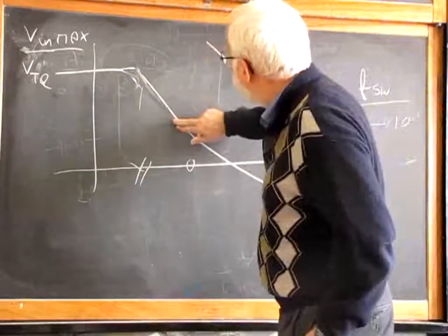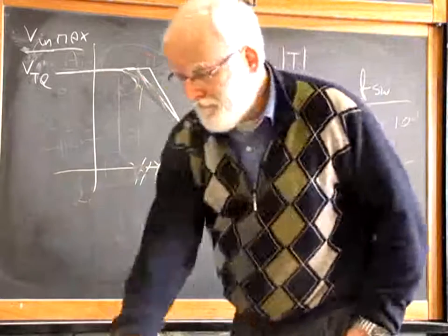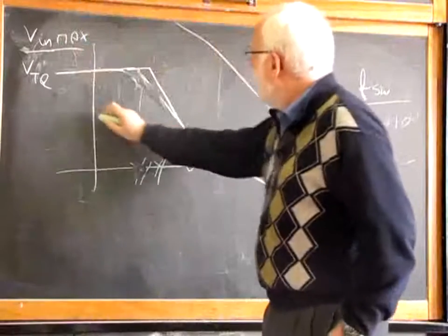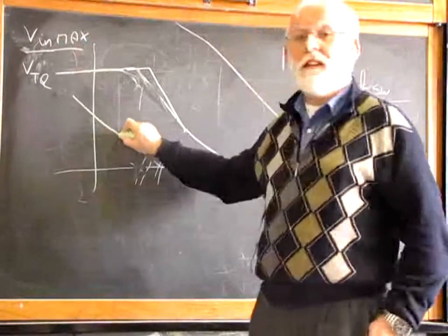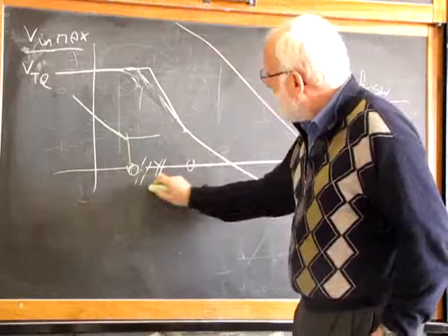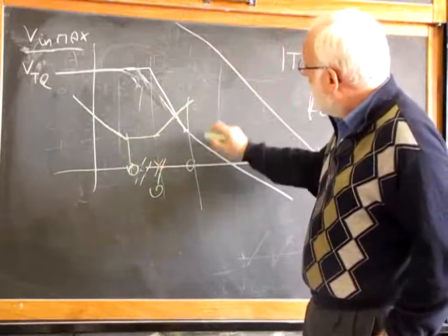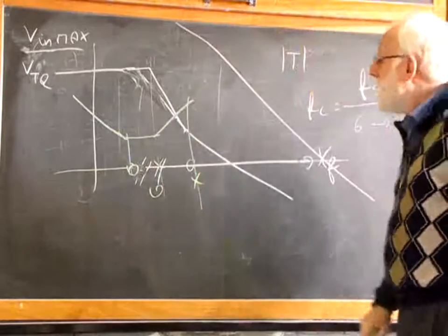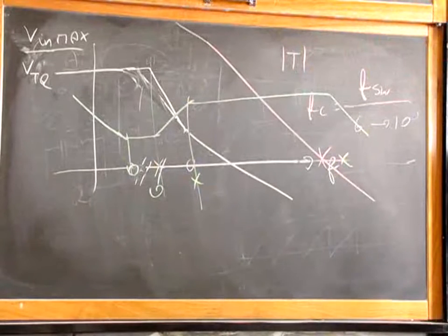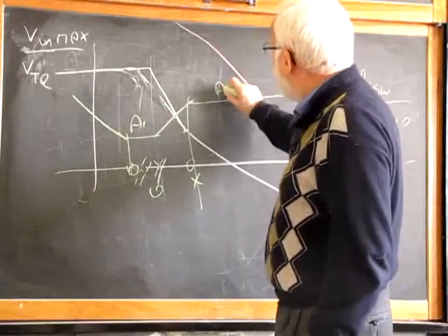I have to admit that this story is not true. So, I know, I don't put the drawing to scale, that my compensator should provide me with an integrator, one real zero over here, a second real zero on top of the two complex conjugate poles, then over here a pole to cancel the output capacitor ESR, and another pole over here. You know that this pole and thing is here. I just need to find out how much is A1 and possibly A2.